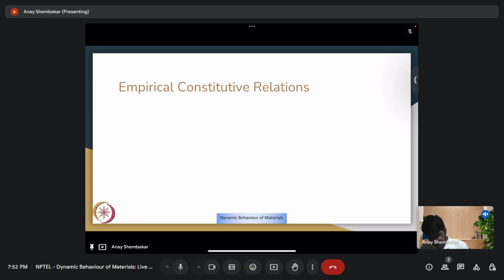So usually, at low and constant strain rates, we have sigma equal to sigma naught plus K epsilon raised to n. This is basically your work hardening expression. We've already seen this in previous weeks' lectures.